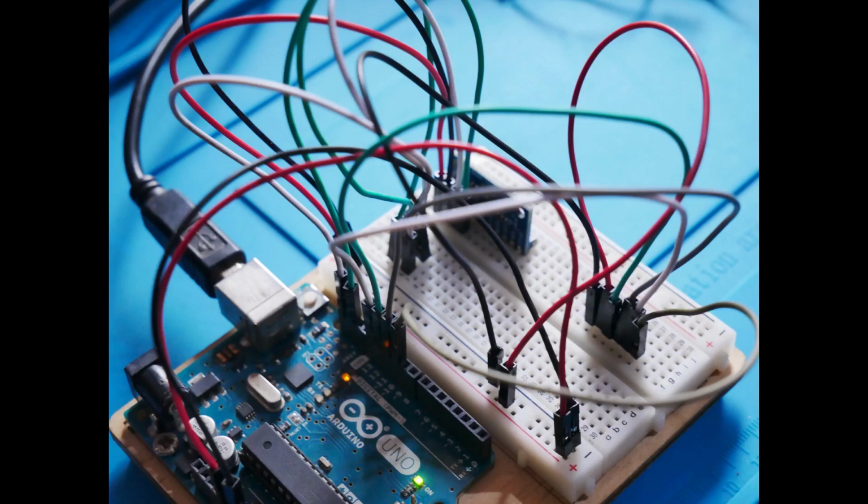The other thing that's also very important is the baud rate. Baud rate refers to the speed at which data is transmitted over the serial connection. It represents the number of bits per second that can be sent or received. The Arduino and the computer must have the same baud rate settings to ensure proper communication. Common baud rates include 9600, 115200, and others. I'll demonstrate that here.